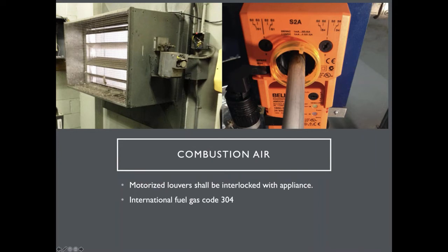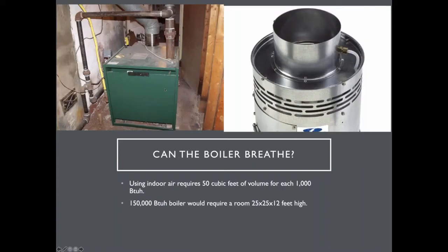They've kind of changed that since then, but you still need to verify that this thing is open before the boiler fires. What about if you have a residential boiler, and a lot of times people want to try to gather some of the space in there and make it a man cave or whatever it's going to be? Well, when you put walls around a boiler, the boiler can't breathe.